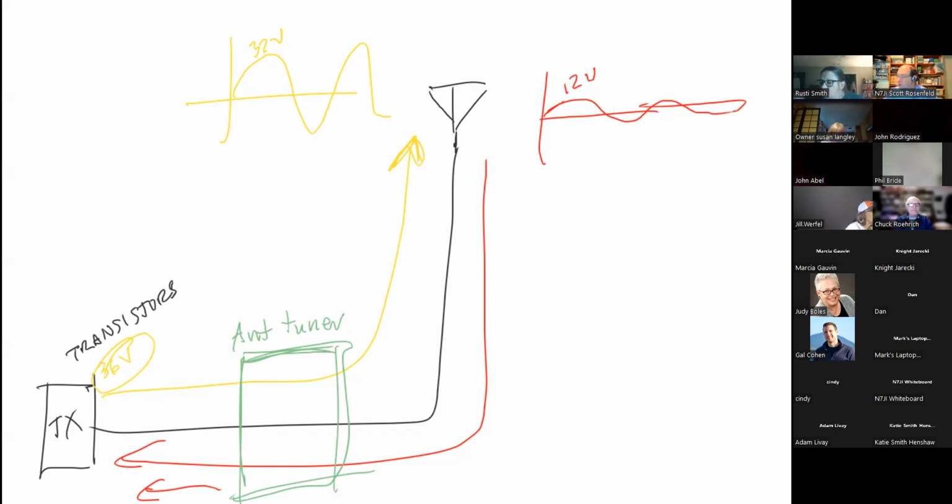What happens to power loss in a feed line? It disappears as heat. Why is it important to have low SWR when using coaxial cable feed line? Because loss turns into heat. Heat does not make a transmitted signal.